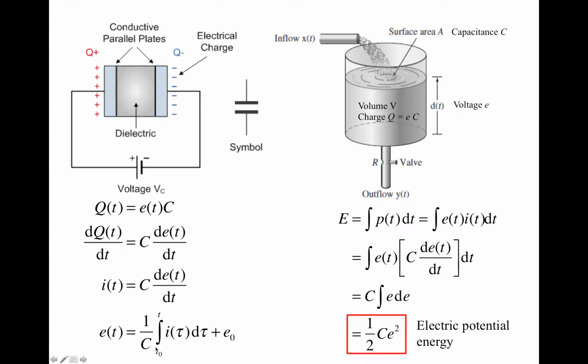So if you write this temporal integral as, for example, t0 through t1, and t1 is before t, then this integral gives you the voltage at time t1. And then you have another integral that goes from t1 to t. So the voltage at the current time t depends upon the history of the voltage. It depends upon the past voltage. So a capacitor is a device that can remember past voltages. It's a device that can have a memory of past voltages.